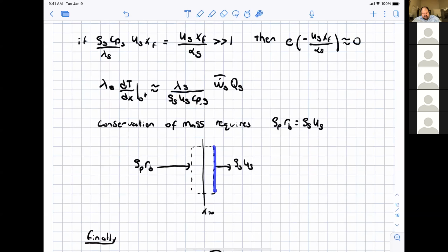And basically, you could do a control volume at any point, even across the surface. If it's across the surface, you can show that the density of the propellant times the burning rate is equal to the gas phase density times the blowing velocity of the gas coming off the surface. So the mass flux going in from the condensed phase side is equal to the mass flux going out of the gas phase side. I could draw this control volume anywhere in the gas or propellant, and the same would be true.